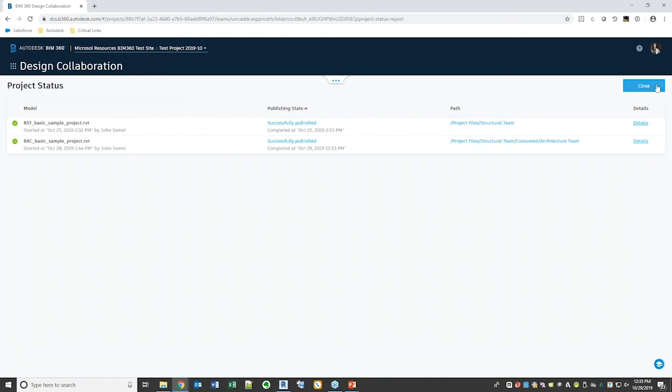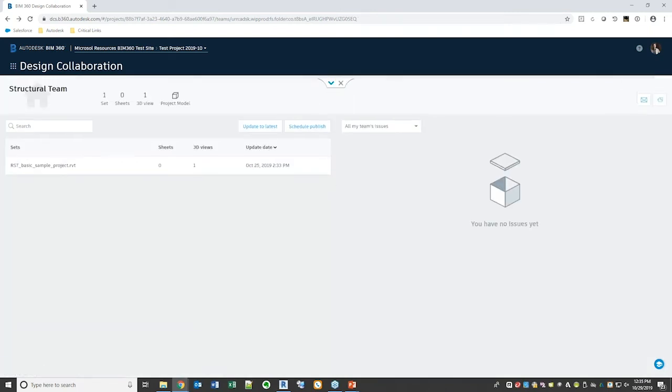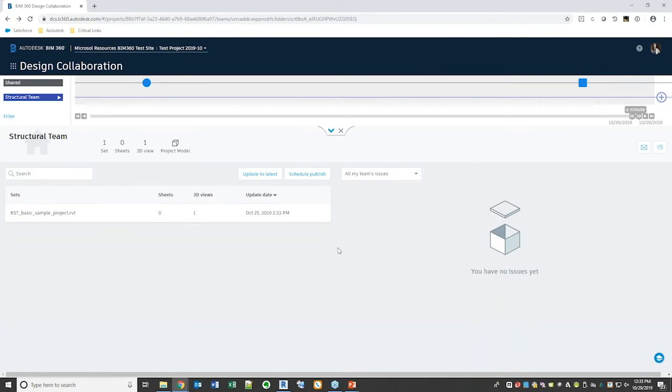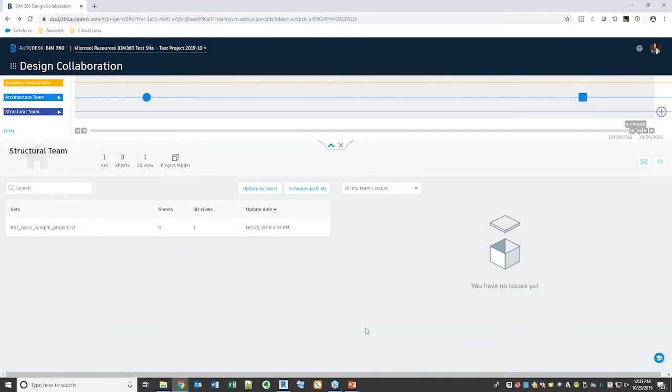Another recent addition is that you can actually add Revit models that are not enabled for collaboration for Revit now. This is another new feature. I believe it was added in August. So the idea is that if you have a Revit model or even a Revit LT, someone is not working with the BIM 360 design portion, they're not working with the Revit collaboration portion, they can still upload a model and you can still make a package and you can still share it and use it for linking.